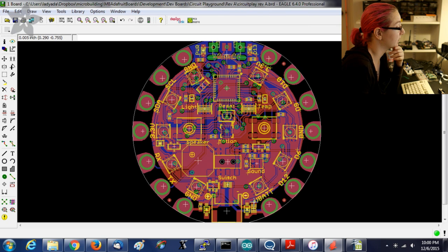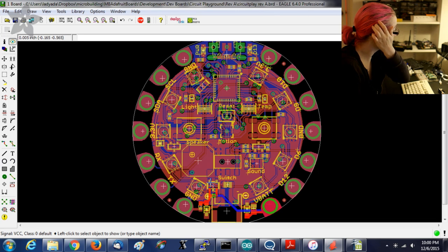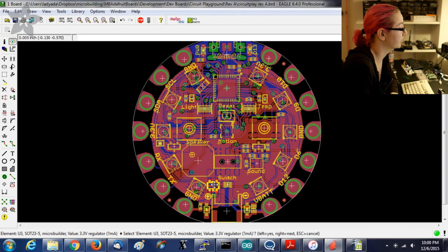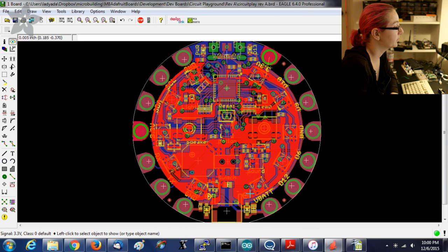And then here's actually that Schottky regulator area. You can kind of see this USB power snakes all the way around with a nice thick trace, comes in here, feeds into this very small regulator, and gives you 3.3 volts.